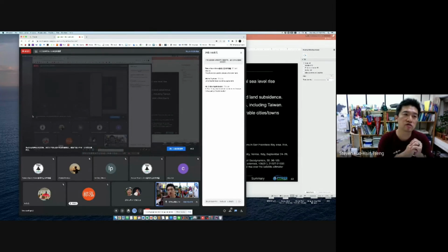For example, you want to measure the height of a canopy layer over the forest, or over a paddy rice field. The last time the satellite flew, you were measuring very short vegetation, and then the next time it becomes higher, so you are measuring another kind of plant. You are not measuring the same thing. So the coherence tells you, please don't use this area. It gives you a hint to avoid which part. Do not try to solve it.